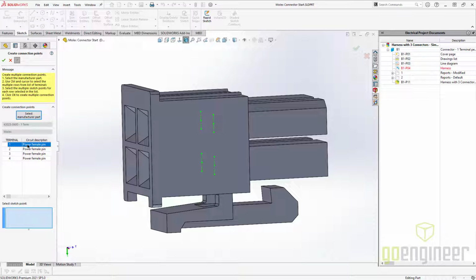All right, so in 21 and older versions, the way that I like to go about it is I right-click over the first line there, say Create Connection Point, and pick out the first one there, which I'm guessing is that one because we've got a flat on the side there. When you do that, it adds the C point, if you've ever done any routing, but it names it specifically, and we'll look at the naming here in a little bit.